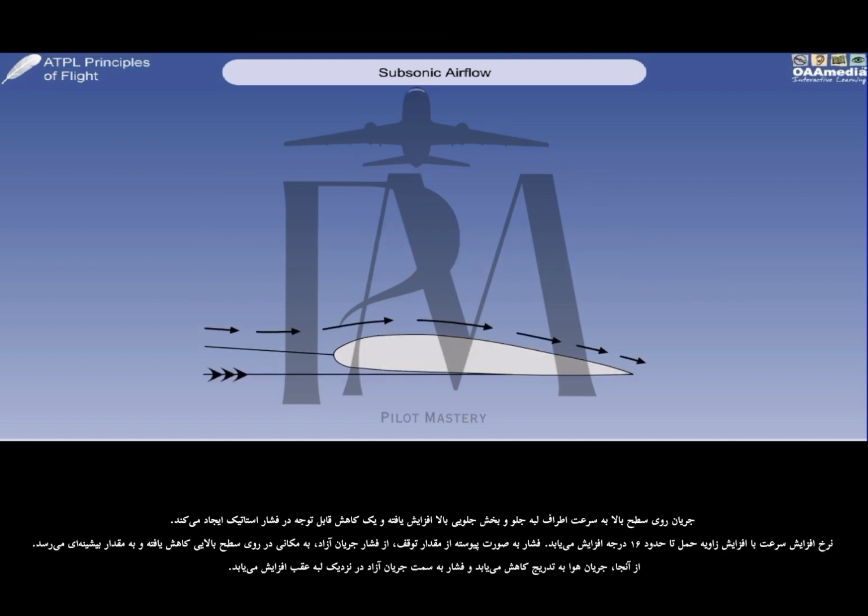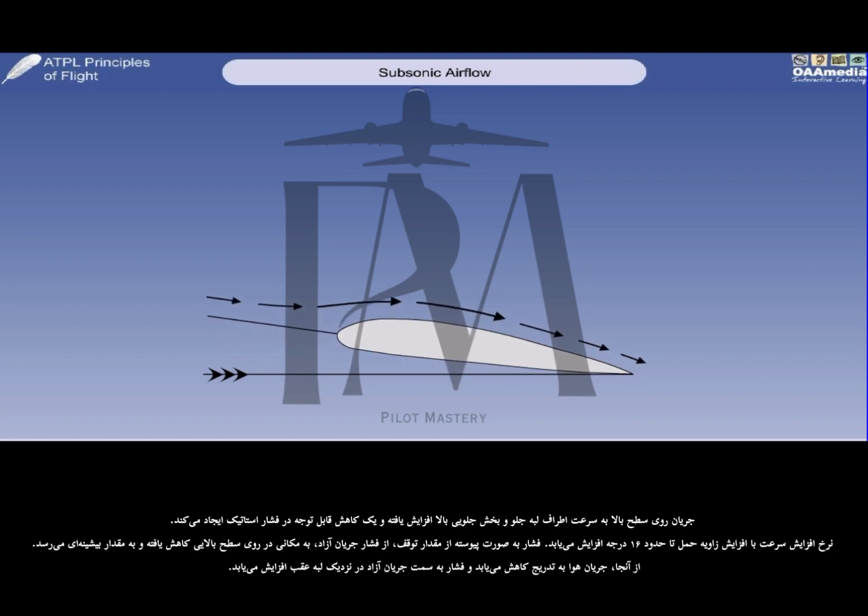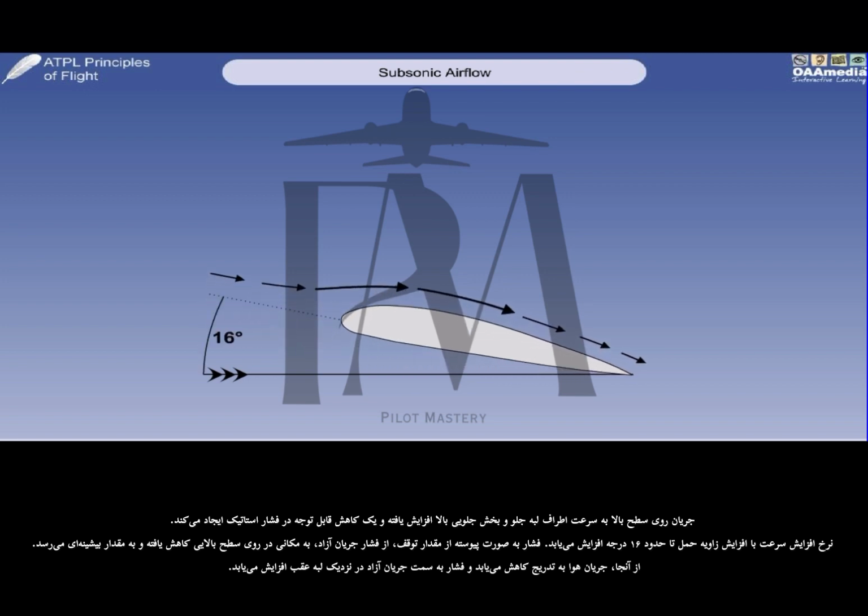The flow over the top accelerates rapidly around the leading edge and over the front portion of the wing, creating a substantial static pressure drop. The rate of acceleration increases with alpha, up to about 16 degrees. The pressure reduces continuously from stagnation value, through free stream pressure, to a position on the top surface where a peak value is reached. From there, the airflow decelerates progressively, and the pressure rises back to free stream near the trailing edge.